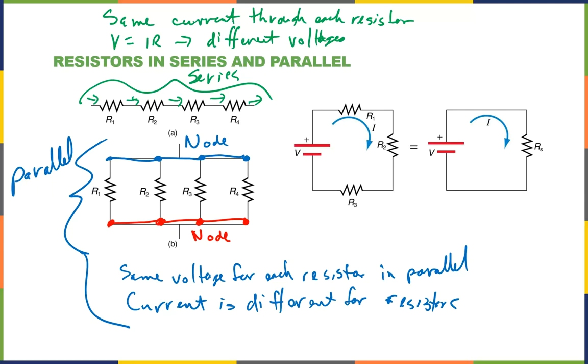With resistors, we often will calculate an equivalent circuit. So here's an example with a total of 3 resistors in that circuit. I'm going to erase my box. Just that one there has 3 resistors. If I want to calculate how much my total resistance is, I say, well, the battery has a certain voltage, and there's a certain current that's drawn through those resistors according to Ohm's law. And so each one of these resistors, what arrangement is this? Is this series or parallel? Series. Okay, so this is series.